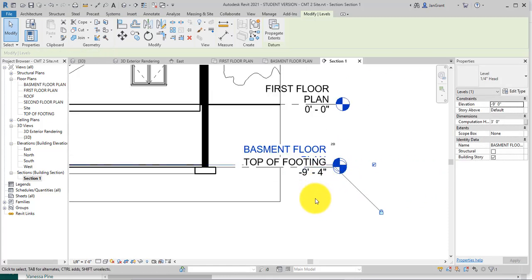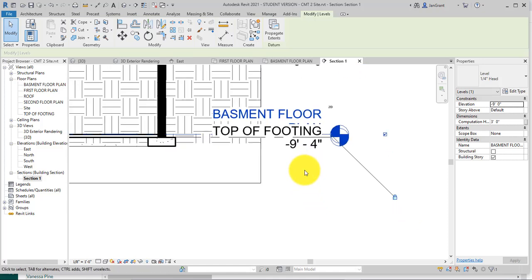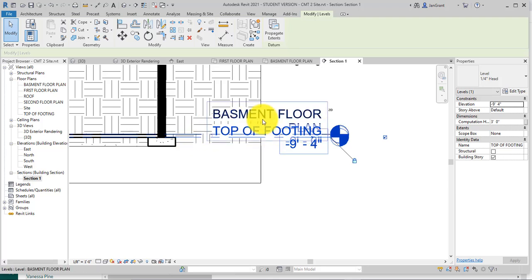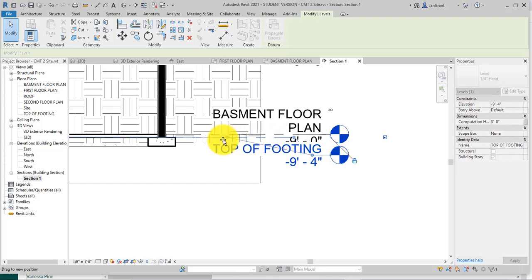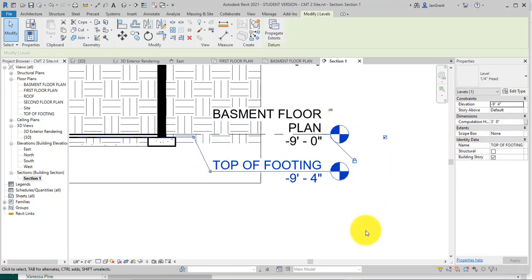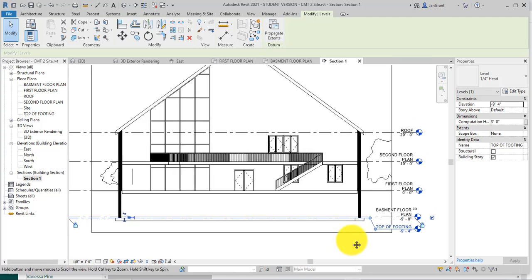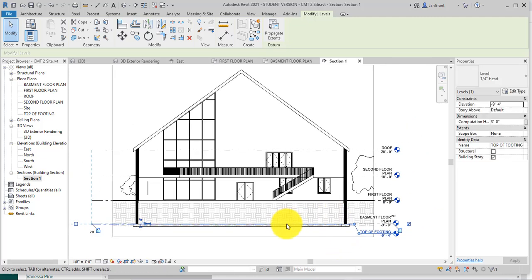Again, we'll need to pull this down if we're going to use it for our section. So we can click on the top of the footing, click on that little zigzag kind of elbow, and use these blue grips like we did in the other section elevation to pull them apart and see the section. Awesome. Okay, let's go get the dirt out.